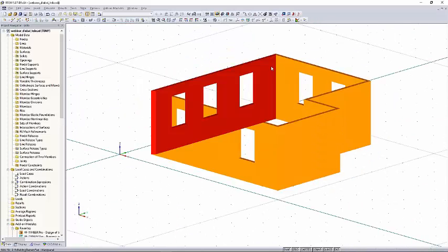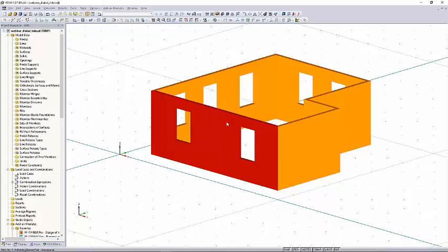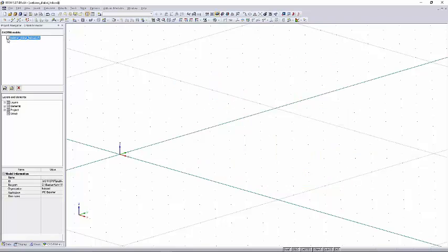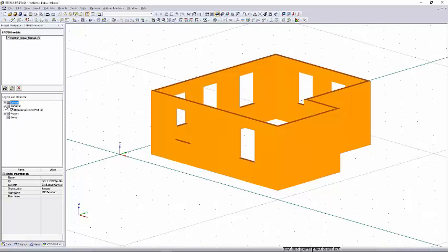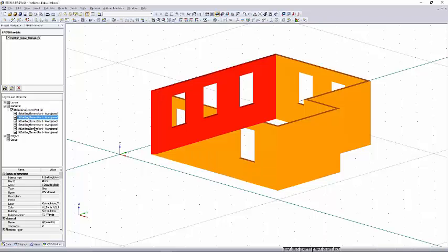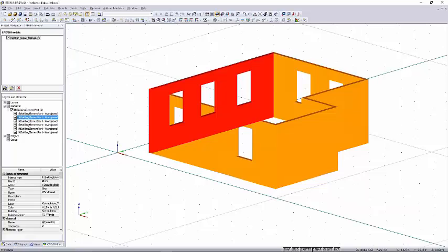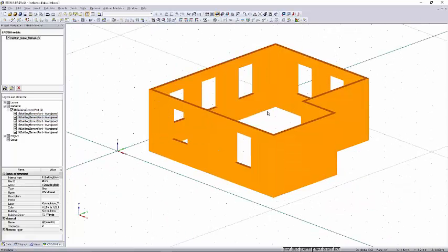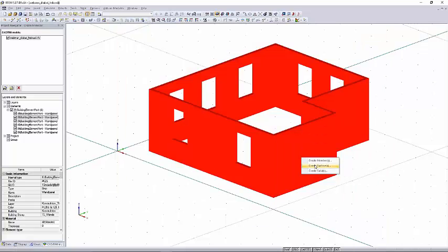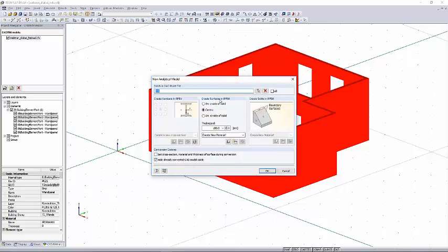So these are the IFC files I got from the hsbcad, and now that I enabled the CID BIM module, I'm able to control all the elements that are in the structure. If there would have been parts that are not usable for me, I could deselect several parts. This is all controlled via this box here. And now that I have just walls, which is perfect, which is the one that I needed from the other software, I can right-click on these files and create a surface.